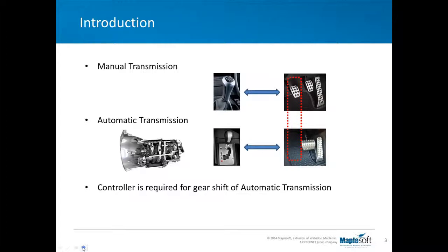The engage and disengage process of the clutches is usually performed by the corresponding hydraulic actuators. The hydraulic pressure applied onto the clutches regulates the torque which can be transferred through the plates. This torque is also called torque capacity, and it means that by increasing the applied pressure, the torque capacity can be increased. So to fulfill the engage and disengage process, a controller which can minimize the disturbances is required.